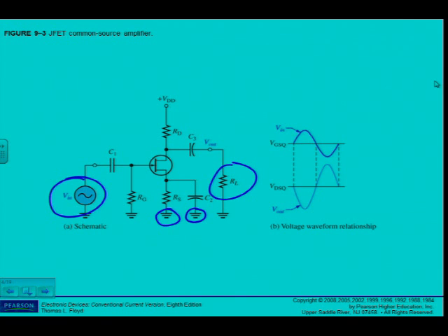Alright. Also, if I look at the input and output signals, as they are shown here, input signal, output signal, I can see it's amplified on the output, and also the same as for the common emitter amplifier, it's 180 degrees out of phase as well. Alright, so let's refer back to the textbook so that you can mark what I've marked there.